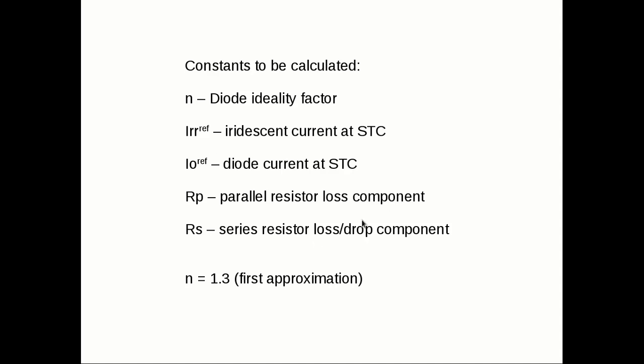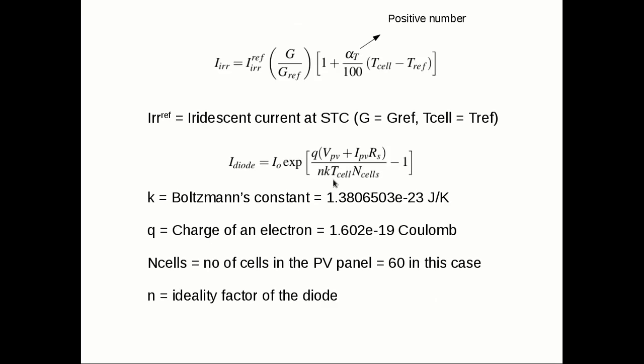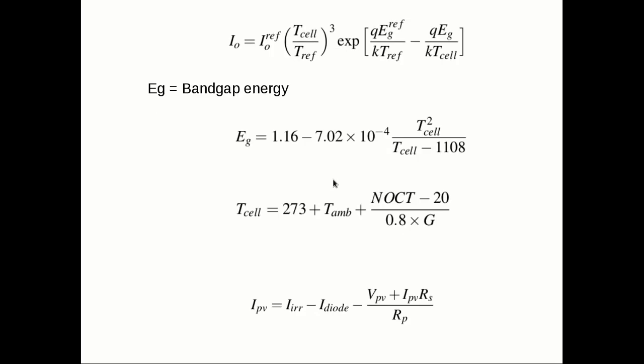All the manufacturer tells you is what is the power at maximum power point at STC and nominal operating module temperature. It does not tell you other things. What we would normally do is we would take all these equations that we've actually derived before and solve them. Now, these are non-linear equations. If they were linear equations, you could just solve them simultaneously. But with a non-linear set of equations, we have to solve them by some technique like Newton-Raphson method. Now, if you look at a paper on solid-state device physics, they will actually do so.